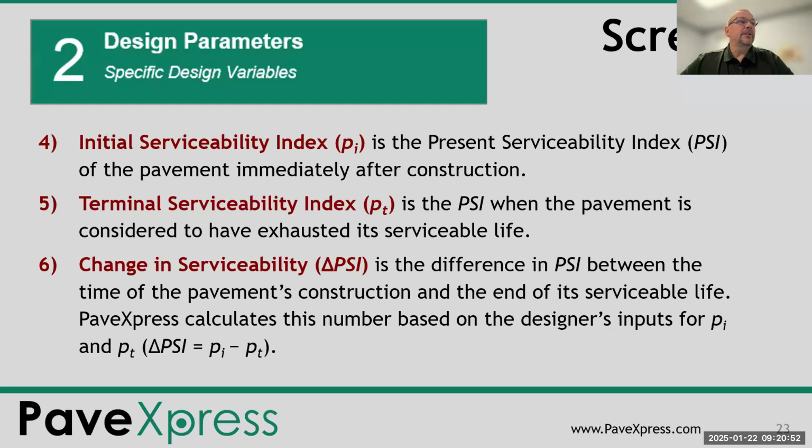The initial, terminal and the change in serviceability, we talked about this a little bit, but the initial is right after construction. The terminal is when it's exhausted and you're at the end of your serviceable life. And then you need that change in serviceability for calculating your structural number.